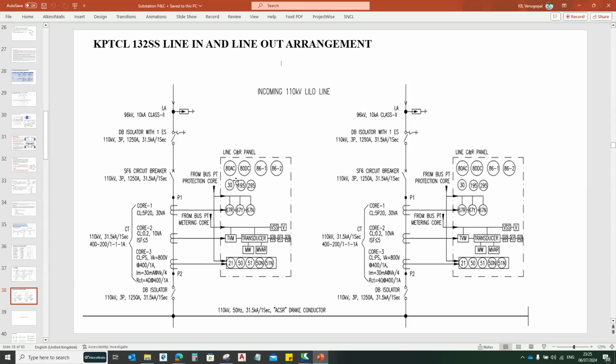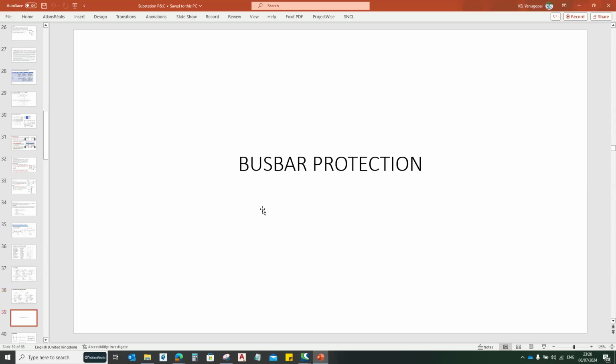So this is about the complete 132 kV level. If you go to the next level, 275 kV as well as 400 kV substations, along with the distance protections you may also come up with a second main protection, maybe a unit protection or non-unit protection, but operations will be more or less similar. So this is about feeder protections.